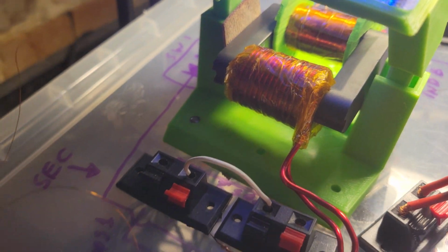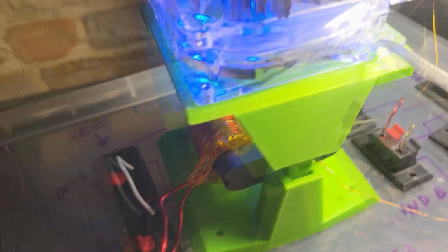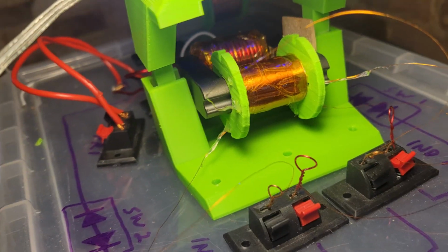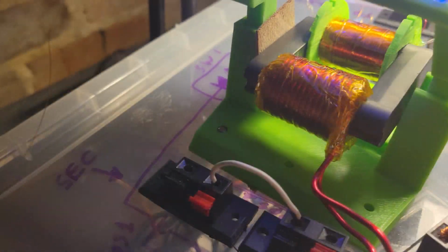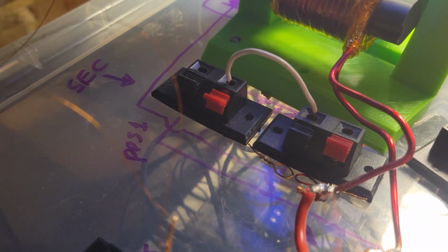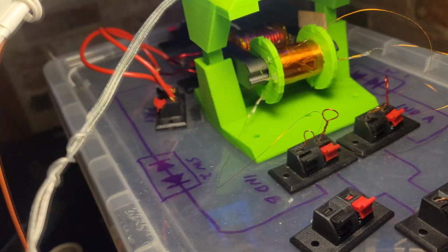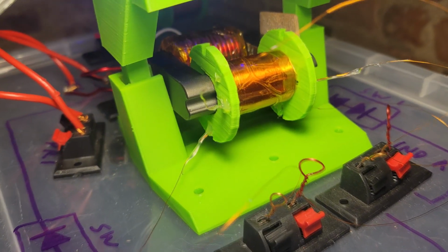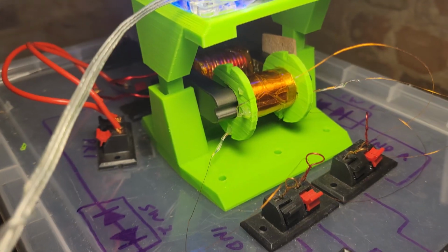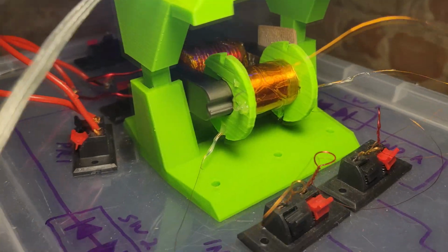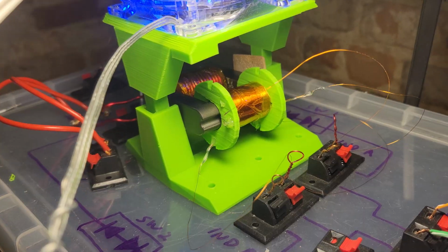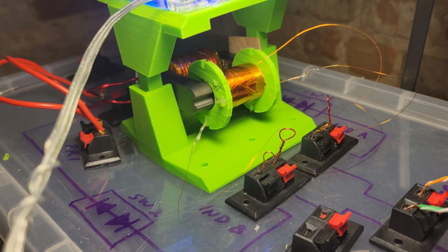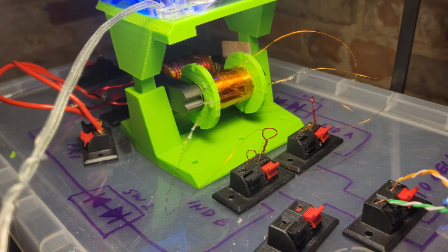We're trying to step up the voltage high at the secondary and choke it with a small inductor, whereas maybe we need a small secondary, a small step up of, let's say, just enough voltage to power the system, whereas the inductors need to be twice as big, 3 times, 10 times as big, who knows? But the magic is in the inductors, and especially being an opposite wind like that gives us the waveform we need.